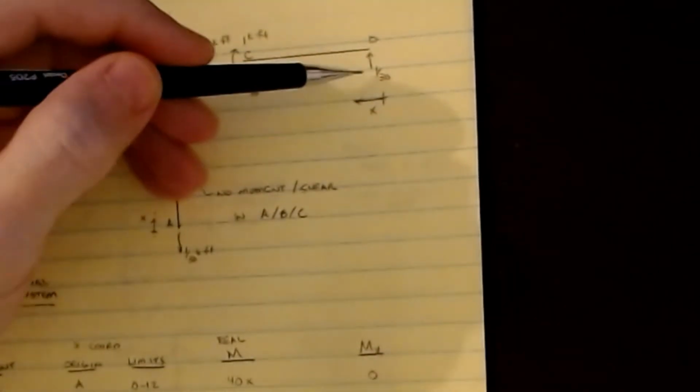So if I go through and play with my reactions, let's take a look at the beam that's here. Then I can cut the beam, and I know that if this reaction is up, then I've got to have a downward reaction of 1/30 to satisfy sum of forces in the y. So the shear at this point just to the right of support C is 1 over 30. At the cut, I also get the moment, and the moment that will balance this 1 over 30 is a 1 kip-foot moment on the end of this beam, because it's 30 feet from here to here, and the reaction is 1 over 30, so that's 1 kip-foot.